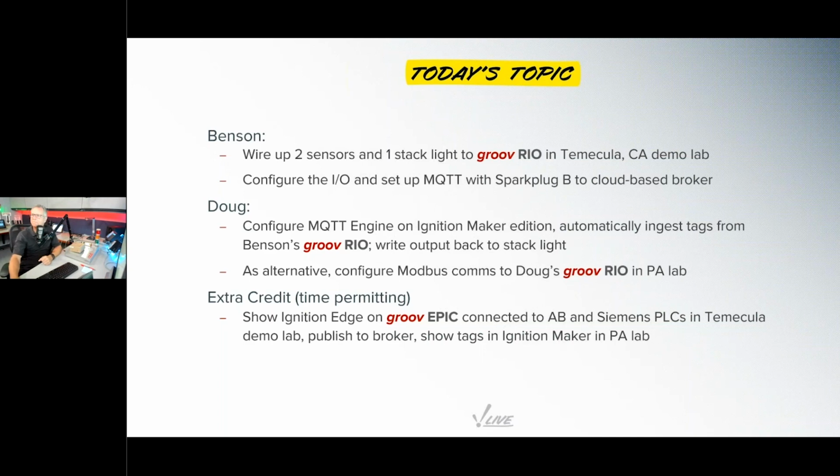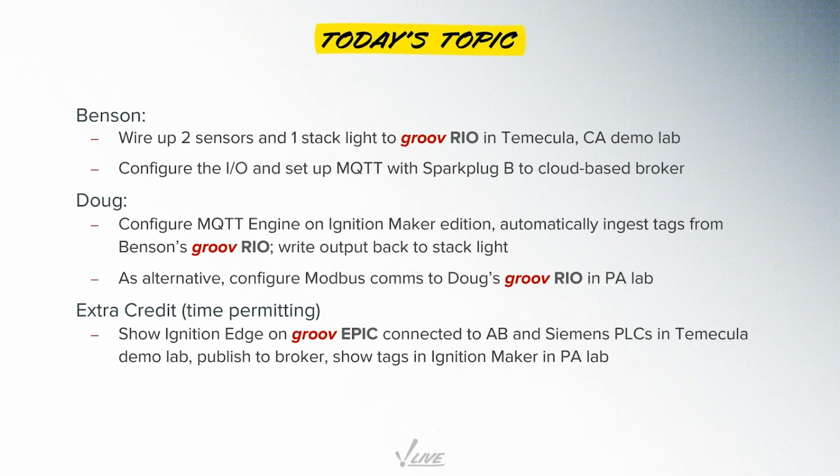And then I'm going to, over here in Pennsylvania, configure Ignition Maker Edition to reach out to that broker and pull in that data that Benson's publishing. We're going to be able to see that live. And then once we complete that, I have a Rio here in Pennsylvania that I'm going to show how you can configure Ignition via Modbus to communicate with it very quickly.